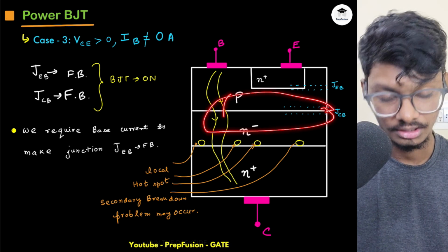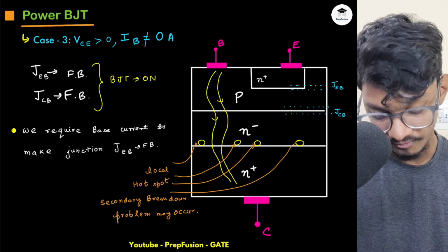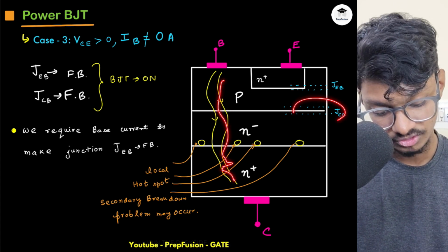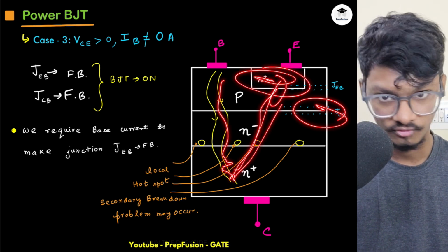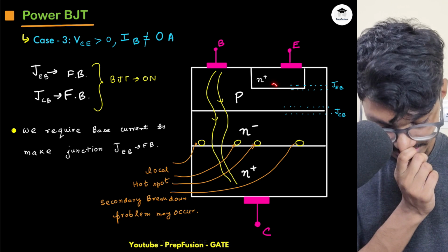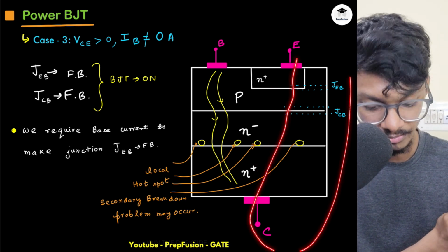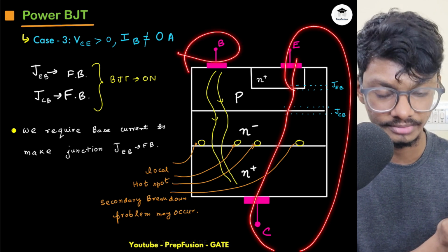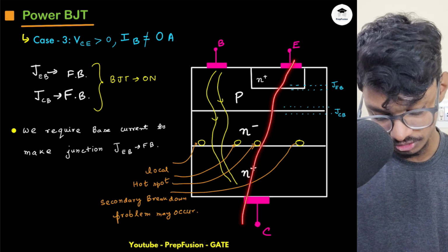This makes the depletion width 0 and the charge carriers will flow. Once they start to flow, this becomes forward bias, and this was already forward bias, so these charge carriers also flow, and the device turns on, because these were my power terminals and this is the control terminal. So this current also starts to flow.